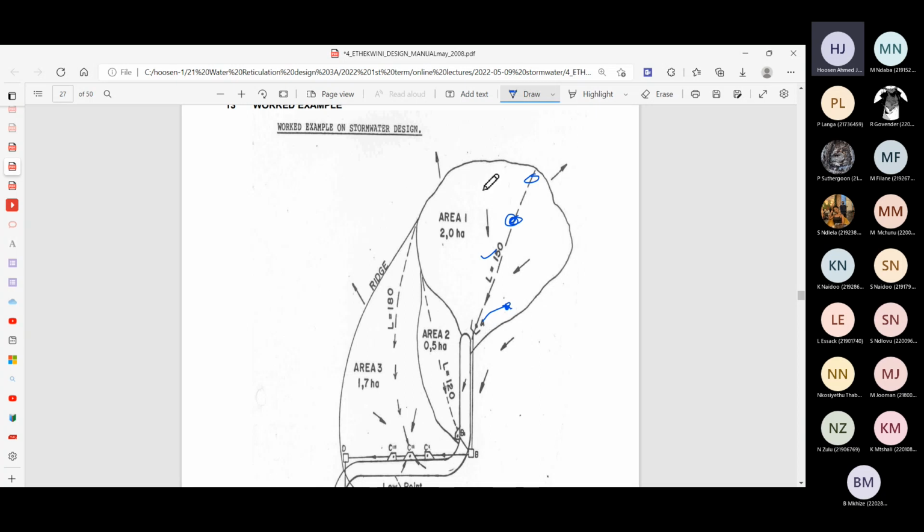And that will only happen if it was raining consistently for 22 or 23 minutes. So once you've got a rainfall of that intensity lasting for that duration, let's say 23 minutes, then whatever rainfall is falling at A is arriving at point A, and even the rainfall at the furthest point is also at point A.